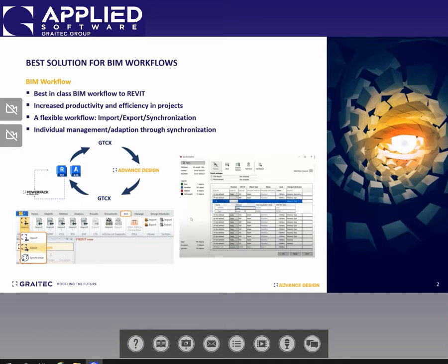In terms of very large projects, that's going to be very helpful to organize your changes and import your model more efficiently. As you see here, our synchronization management tool can also control individual members. So you can accept some of the changes in our synchronization window and ignore some of them. It's going to give you full control of your model import.